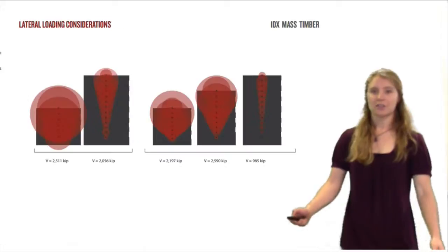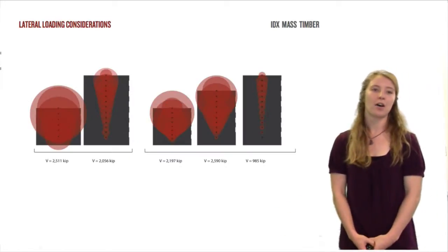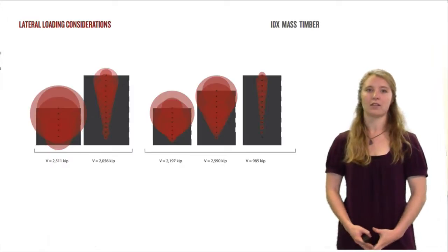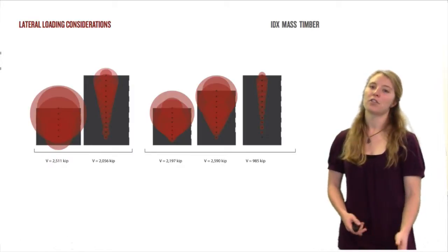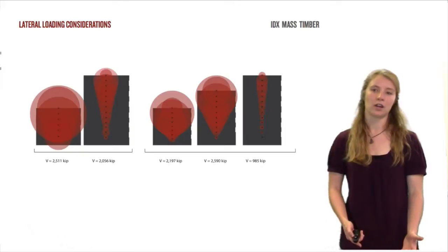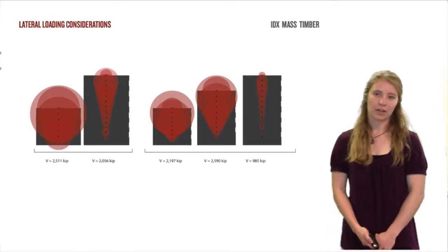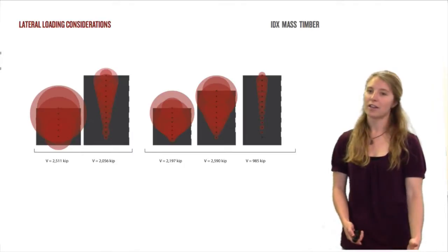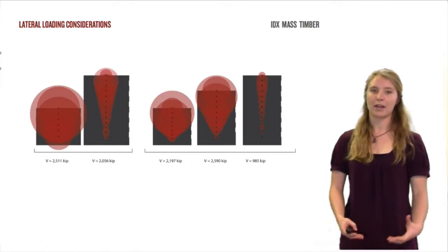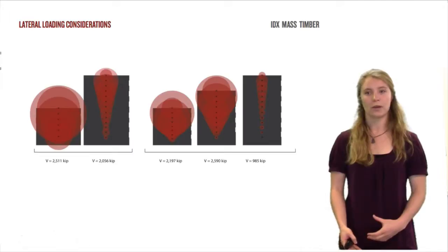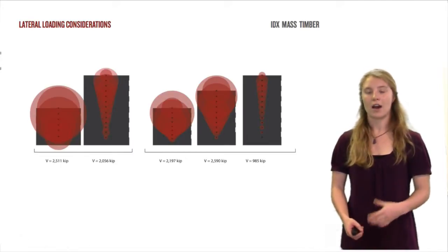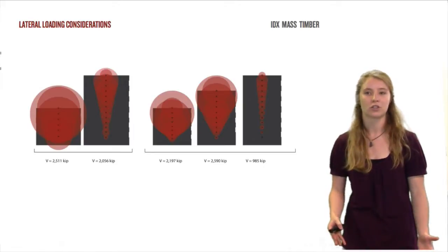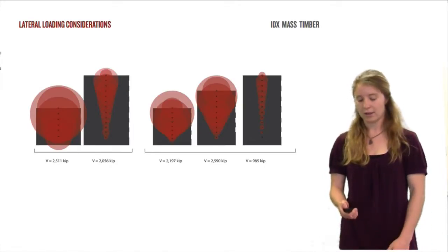Thank you, Errol. So to begin, Errol has talked a lot about how zoning, occupancy, and building type play a role in developing the structural patterns that we see in these buildings. We've also looked at other considerations like lateral loading. Seen here are our 5 buildings with their corresponding vertically distributed base shears. A lot of this is determined by the plan size of the building as far as its floor dimensions, and also the allocation of mass in these buildings. That's why you see a variance between large circles and small circles at different heights.